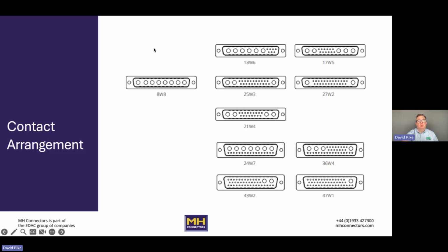And so let's take, for example, this 8W8. This is unique to this connector type shell. If we talk about an 8W8, it automatically will tell us that we are looking at what is a standard conventional 37-way D shell with 8 pins in. You'll notice there is no 8W8 for any of the other sizes. It is a unique classification. So it's like a shorthand for combination D subs. It makes it very easy to understand the product we're looking at.